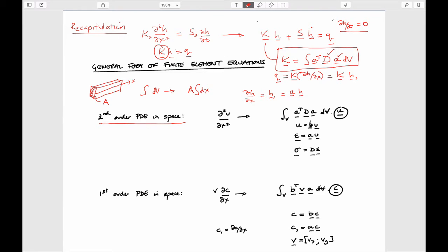Remember, this shape function term was the tent that was mapping all the displacements from individual nodes onto one particular point, and it's what we also call the weighting function, if you remember from last time, that we applied in the Galerkin method. So far we've done everything to be able to define the expression for solving a second order PDE, which is of course what we're dealing with.